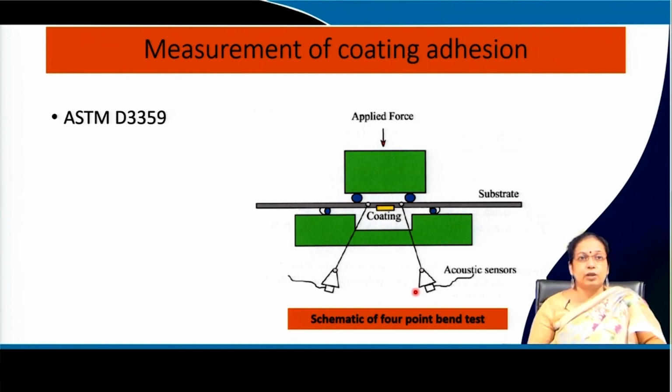On the other hand, if you apply a very thin coating of stainless steel, or if you replace the mild steel with AISI 304 stainless steel, you will find that the degradation probability is very low, and even though degradation is there, the kinetics of degradation is very low. Or you can also apply a very thin layer of tin coating on the surface of the mild steel. Tin has very good resistance to attack by water.